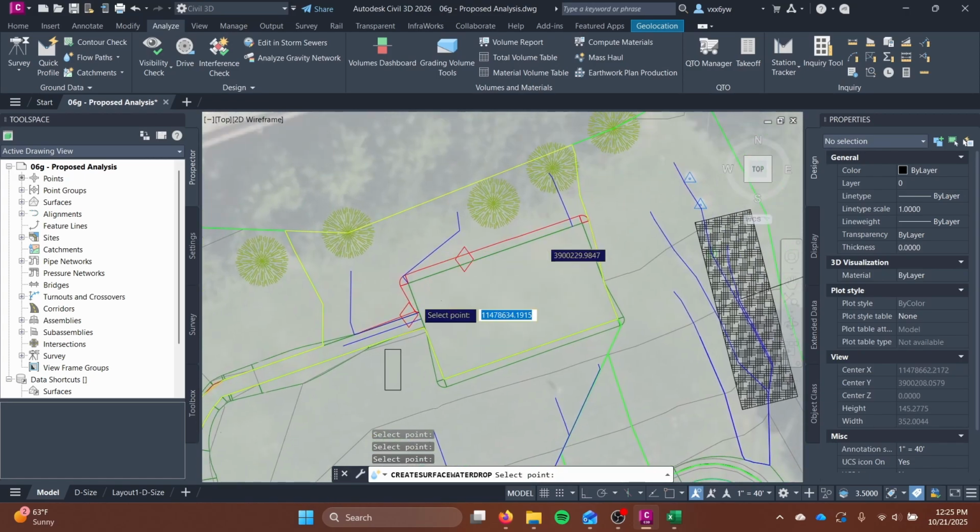You can either include this area in an existing catchment or in its own catchment. I think the best way for you to think about this is to look at which way you'd want your roof system to go. Do you want your roof to be highest in the middle this way and it slopes in the west and east direction? Or would you rather it be highest in the middle this way and slope towards the north and south direction?